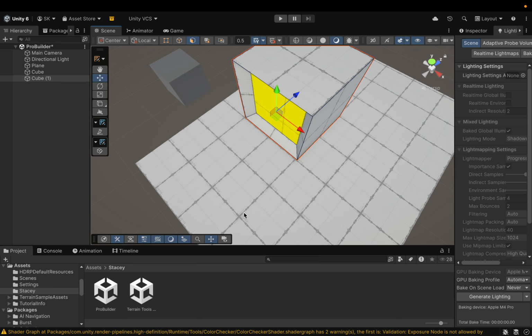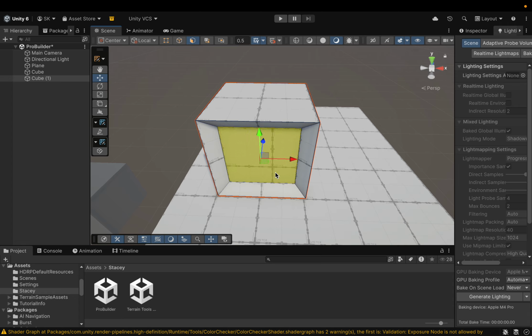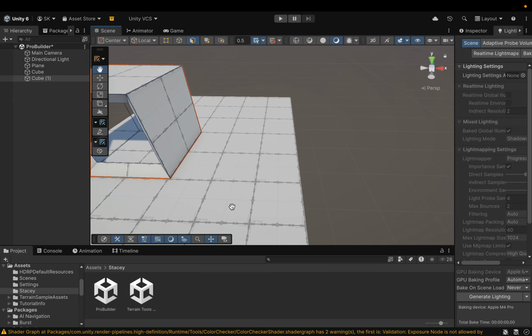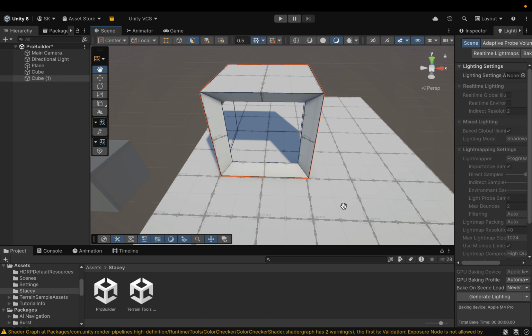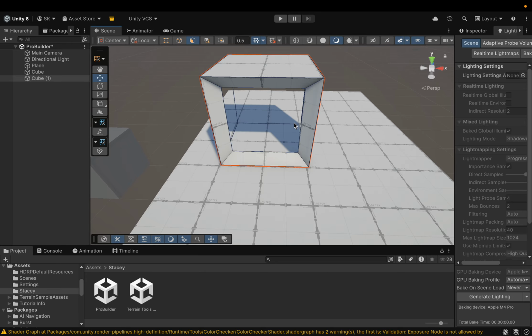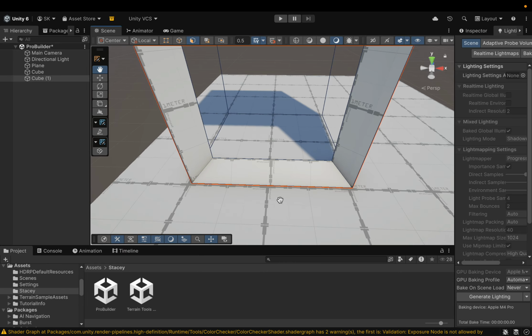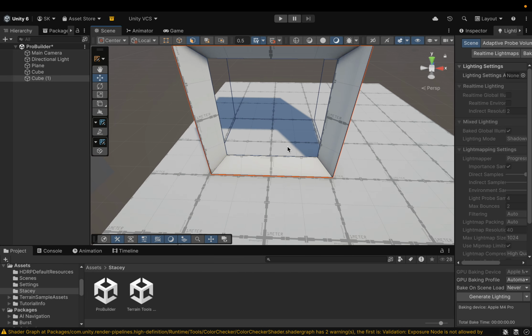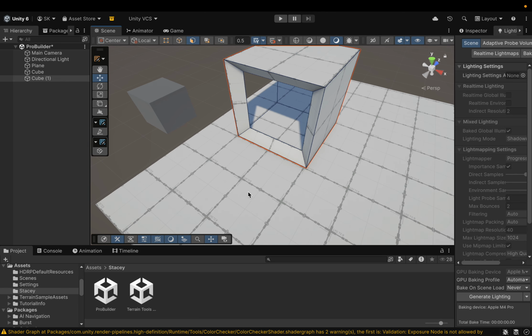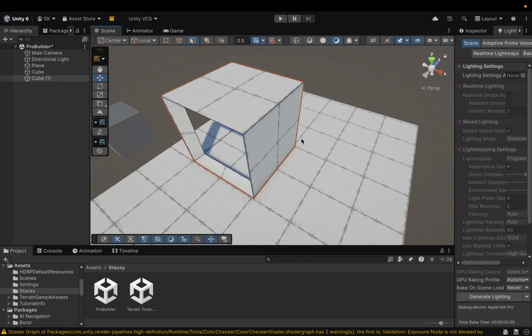You can delete a face by just selecting it and hitting backspace. So now I've got a deleted face. From the inside, I can't really see it because I haven't flipped my normals. If I wanted to flip them, I can also flip my normals here, which I'll show you in the second chapter of this on when we get into more advanced tools. Okay. In addition, like the vertex, I could choose a vertex here, and I can move it out just one point at a time.